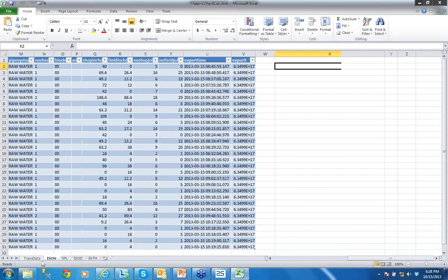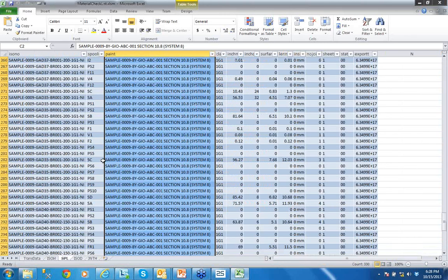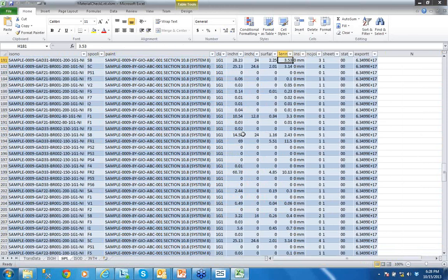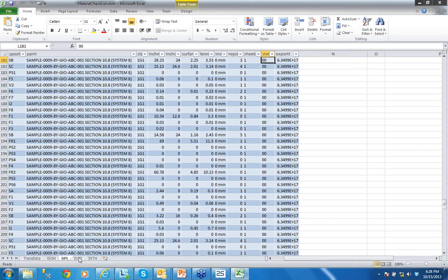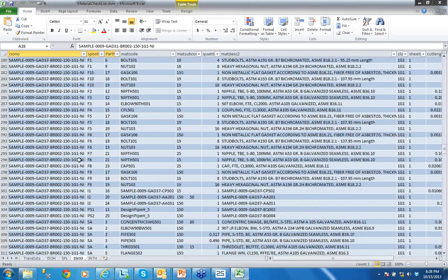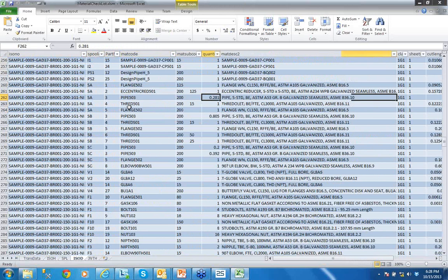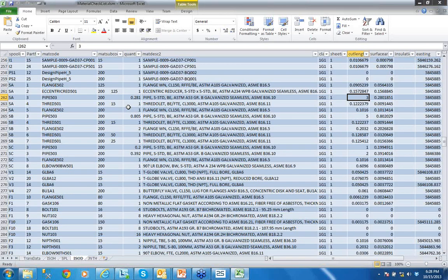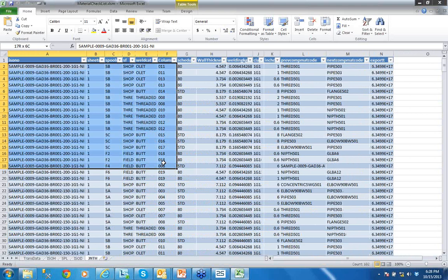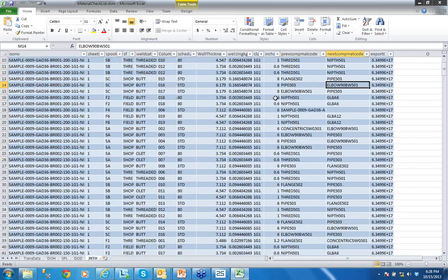We can see also all the detail of the spools with some summary like the BOQ data, number of sheets, where it belongs. I can know also what is this isometric made of, like, maybe this spool is made of a flange and so on, with the full detail of these data. I can as well see the weld table, which will show me the different welds with their unique numbers, and between what and what kind of class it is, what kind of welding procedure it is required, and so on.